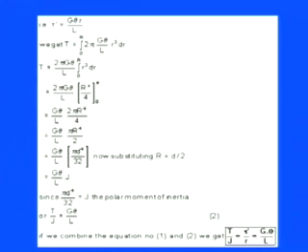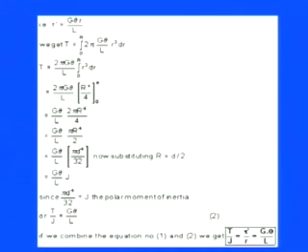As we were discussing, we have the polar moment of inertia, which relates to the effective area under the application of the torque. So J is equal to pi d4 by 32, and this component can be replaced by J, the polar moment of inertia, because it is coming under the concerned area.